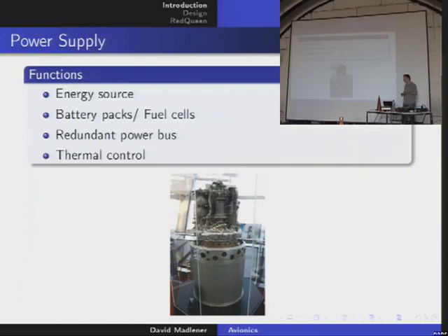And very important, especially for battery packs, you need thermal control. Battery packs are made of devices with electrolytes, and this is a liquid containing especially water. And when water freezes, it just destroys the battery pack. It just explodes. So after that, the battery is not usable. So you have to control the temperature in the compartment where the battery pack resides. The same is the case if it gets very hot, then the battery has to be cooled. And that's what happens to a lot of missions on, for example, Mars. There is a very long winter night, and then the battery pack just freezes over and you lose contact to the vehicle and the avionics.